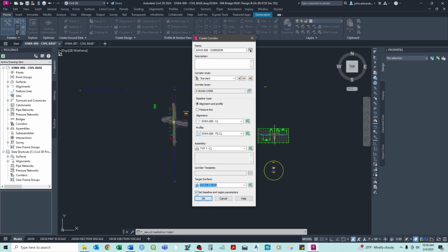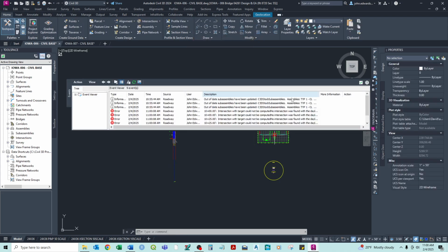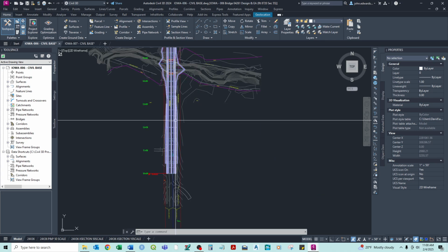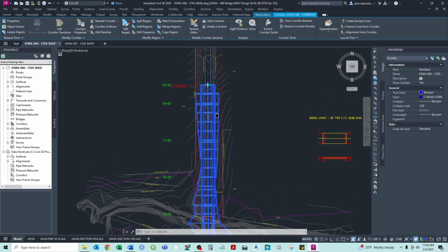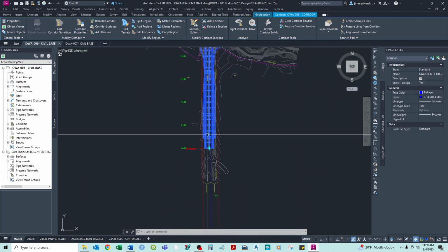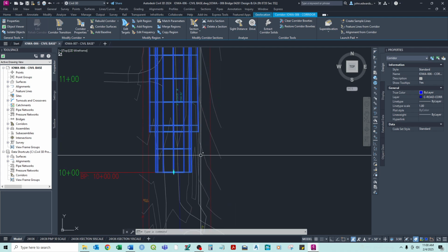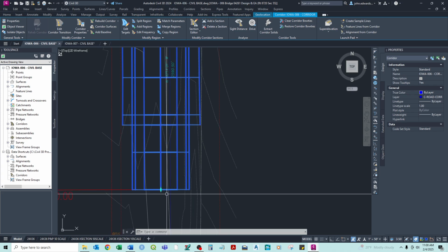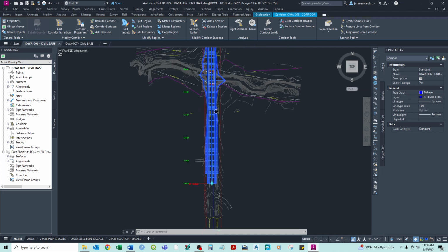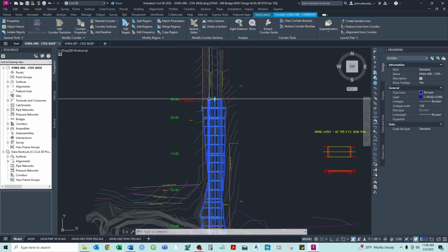You can go ahead and set some baseline and regional parameters for the corridor. We're not going to do that in this video. We'll do that in the next one. So we're going to uncheck that and just hit OK. And then now we have our corridor. So you can see it coming all the way down. Now you'll note here it kind of sticks out a little bit further here than right here. And it did the same thing along the end.